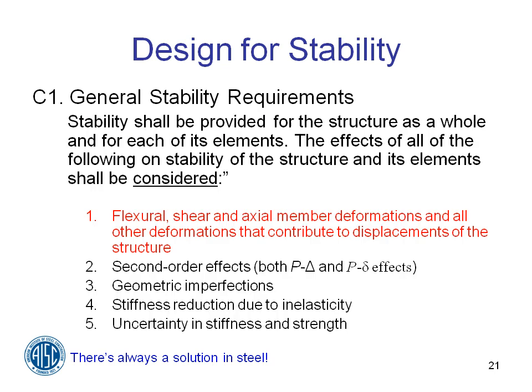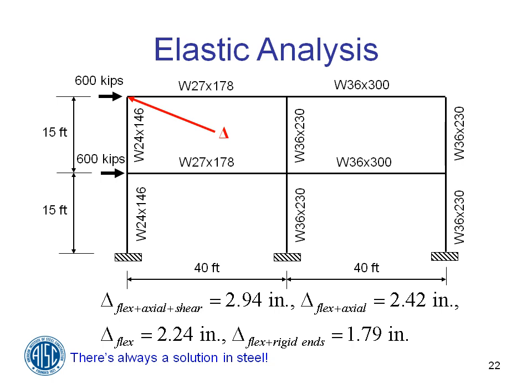All right, so let's look at the things we have to consider: flexural, shear, and axial member deformations, and all other deformations that contribute to the displacement of the structure. I've got this simple little structure, 2 stories, 2 bays, fairly large members, and large lateral loads. And what I want you to take a look at are the deflections that we get from the different ways that we can calculate things.